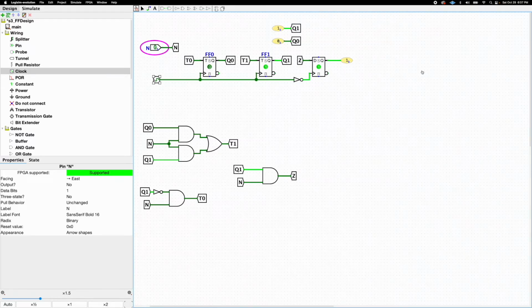The reason being is that these Mealy circuits usually require these strobed flip-flops here. We have a D flip-flop here where we're getting our output inputted to here, as well as inversing the clock. So this is to ensure that the signal is correct. It's not being rushed, not reading anything too early between the clock cycles. And it also holds a signal for 1 full clock cycle, which is probably why we were getting 1 in an awkward place and was confusing me there for a little bit.